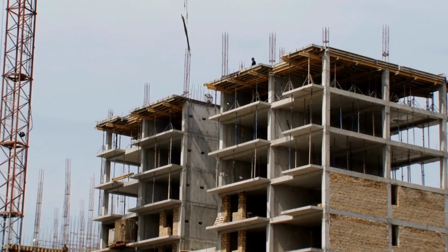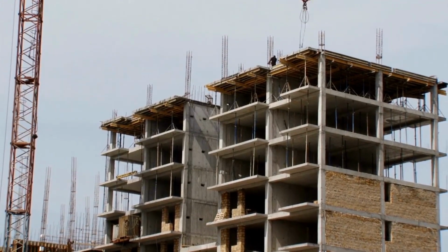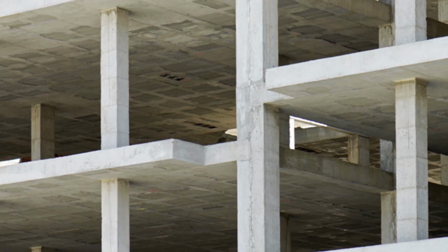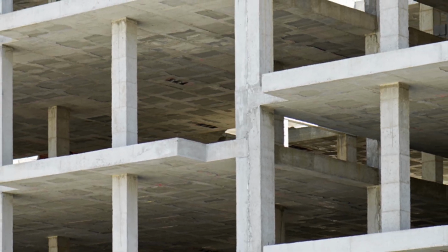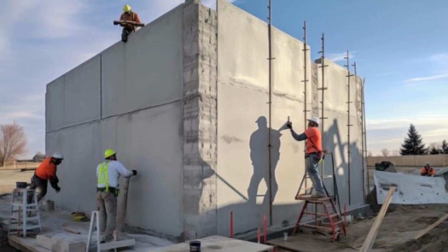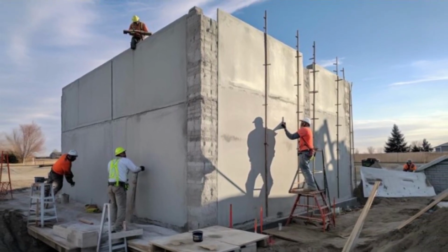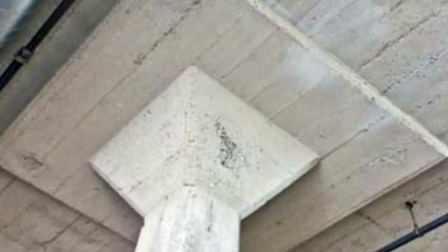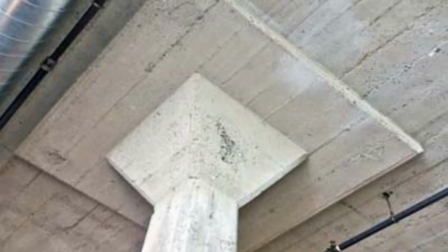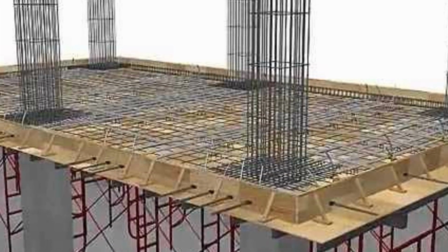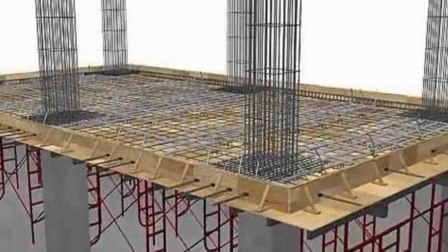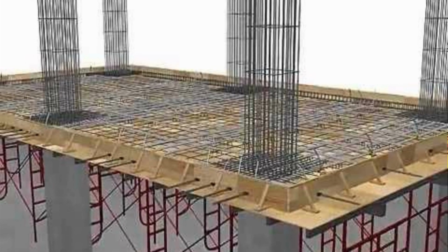This procedure entails producing flat concrete slabs at a factory that can be used to construct a building's walls, floors, and ceilings. You can build a series of concrete columns in the center of the room and along the walls to hold these slabs together, doing away with the requirement for steel beams. You may also add a drop panel to the top of each column so that the slab support structures bear the majority of the weight of the slab.